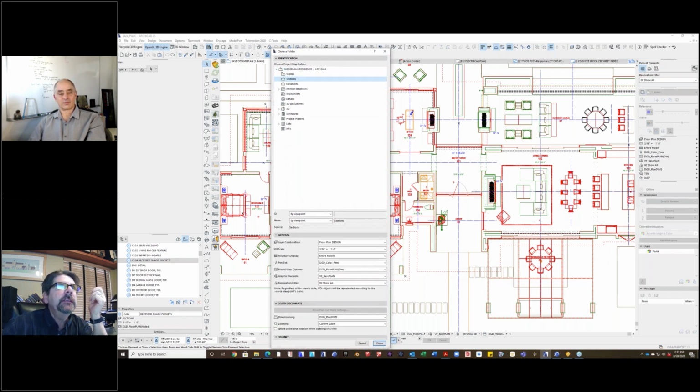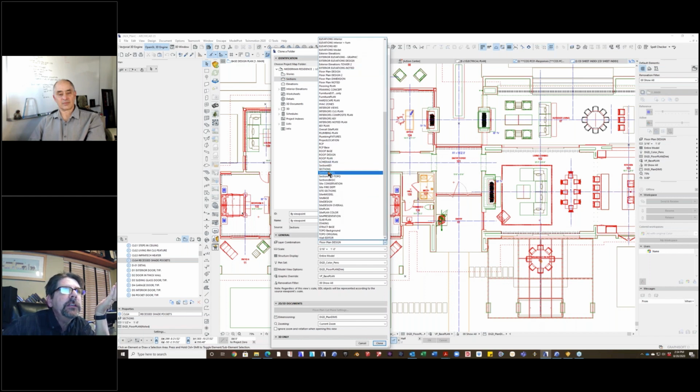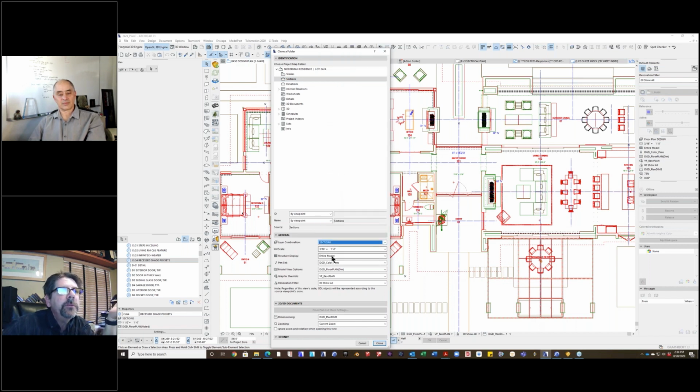And here's the nice thing: when you're doing this, say for 90% of the time I'm going to want section layers. I'm going to want them at 3/16, so I'm going to do the entire model. I can give it a base recipe to follow. And so anytime a new section is created in plan, it will have this recipe. And then I'm free to come back later and say, oh, this is a different section. I need that particular section to show up at a quarter scale, whatever.